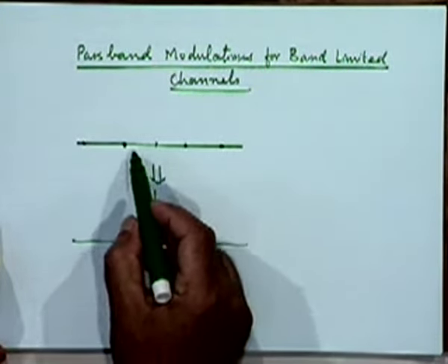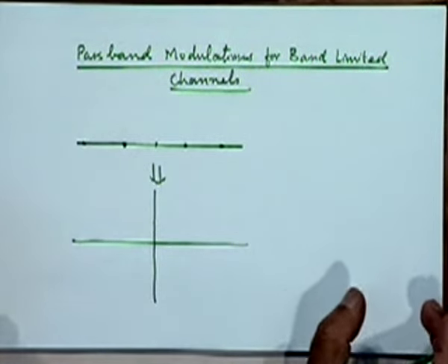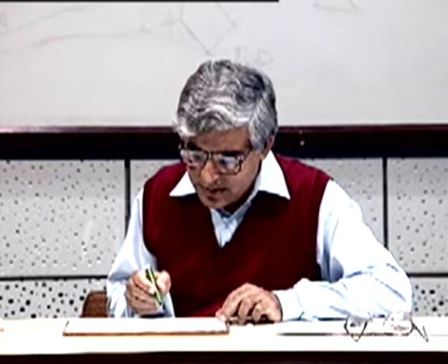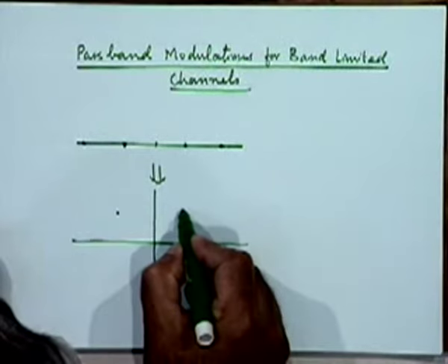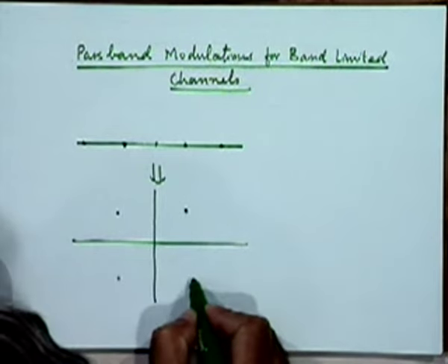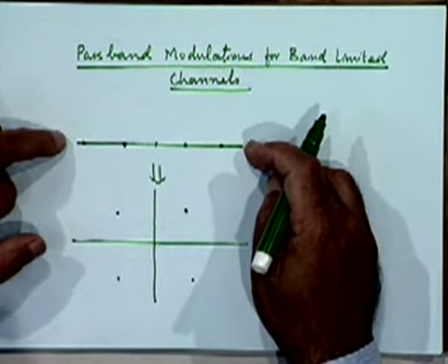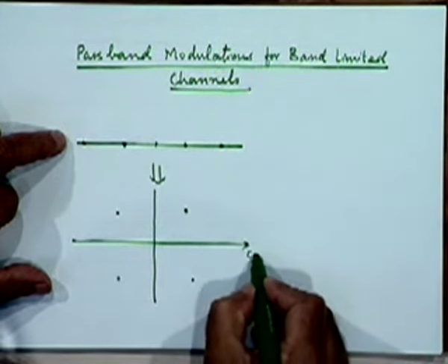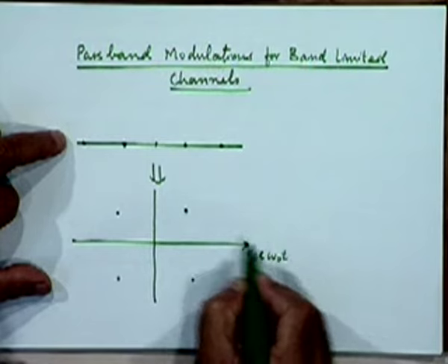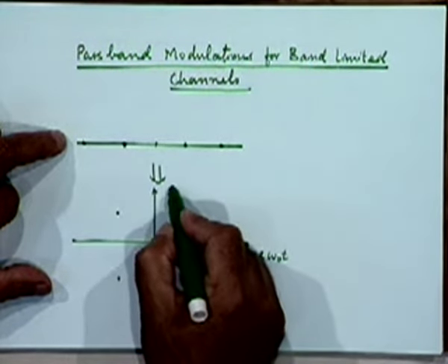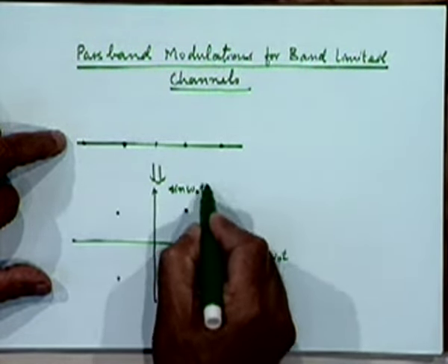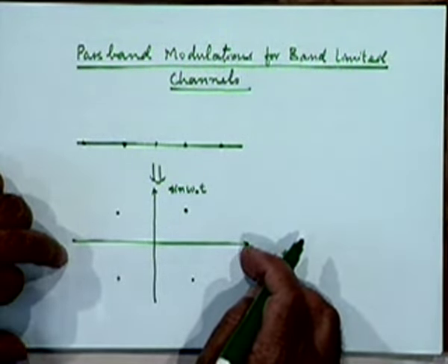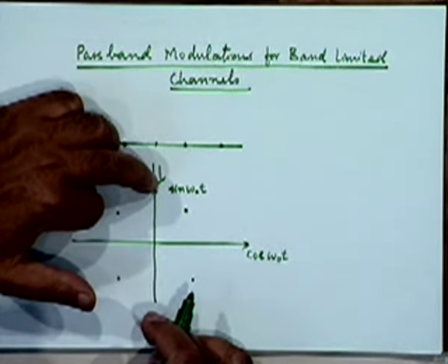Okay. For example, if I have a binary modulation on each of the 2 carriers, 2 quadrature carriers, right, I will get a 4-point constellation which now looks like this. If I have a binary modulation on cosine omega naught t and another binary modulation on sine omega naught t, right, maybe this modulation will be governed by the even data bits, and this may be governed by the odd data bits.